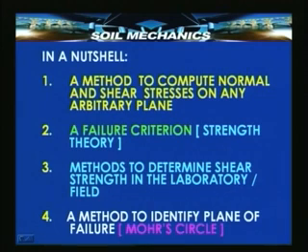And then we need to know what the strength is in order to assess whether failure will take place, and for that we have methods. And then in order to compute the stress, finally we have a nice geometry based method known as the Mohr circle. Incidentally, the Mohr circle itself is based on certain equations which we had developed rigorously, and therefore either we can use the geometrical technique or directly the equations.